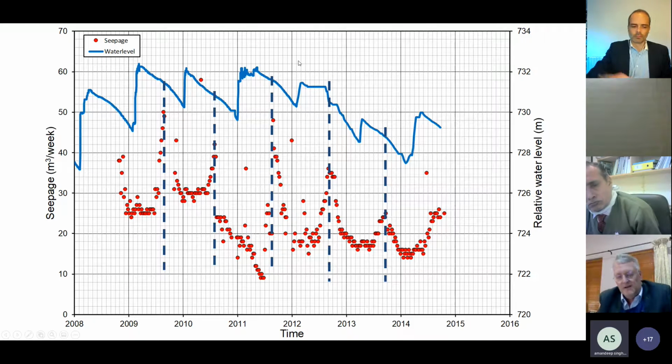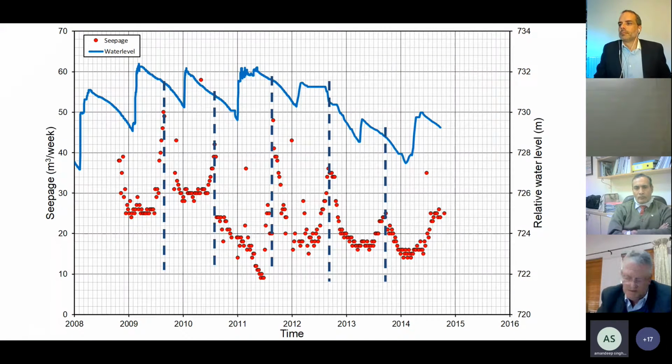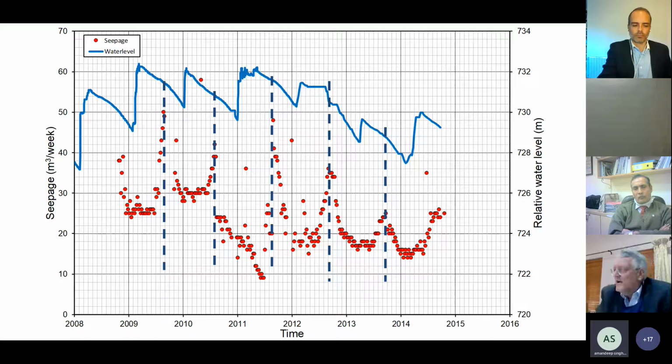If you consider an arch, what happens in winter, due to the seasonal temperature changes, is that it wants to contract and move downstream because it gets smaller. If it moves downstream, you normally get some movement on the upstream side, either in the contact between the concrete and the rock, or in the foundation itself, or you could have a construction joint as well.